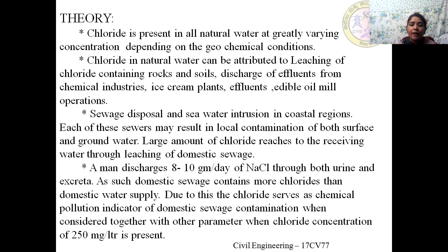When such a thing happens, we say it is seawater intrusion. It has come and added up with the fresh water, so the fresh water becomes salty because it is mixed with the saline water by the intrusion process. This seawater intrusion increases the chloride content of any given water.